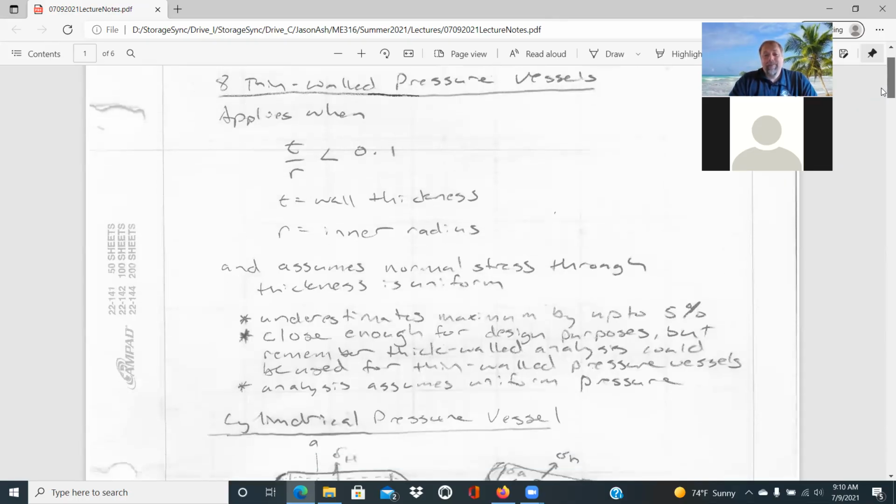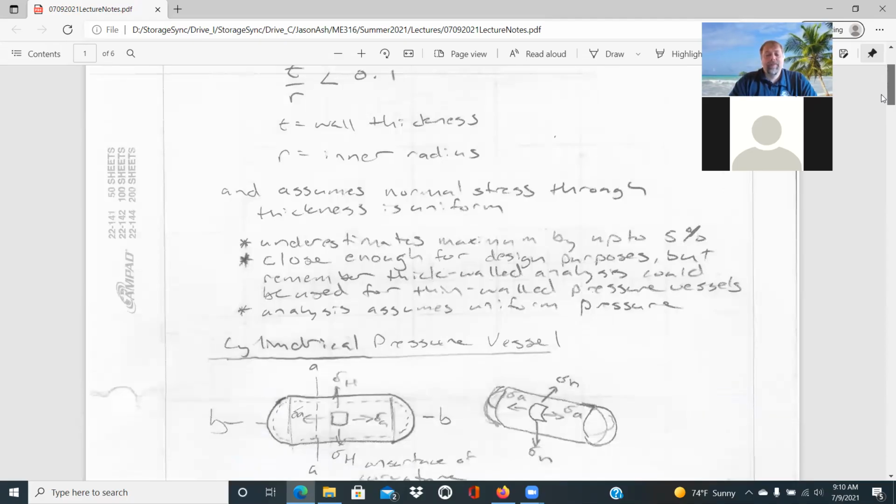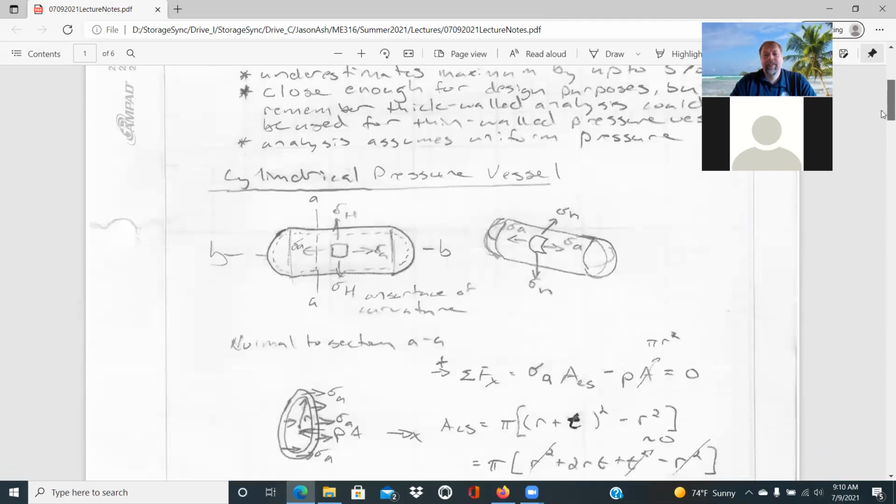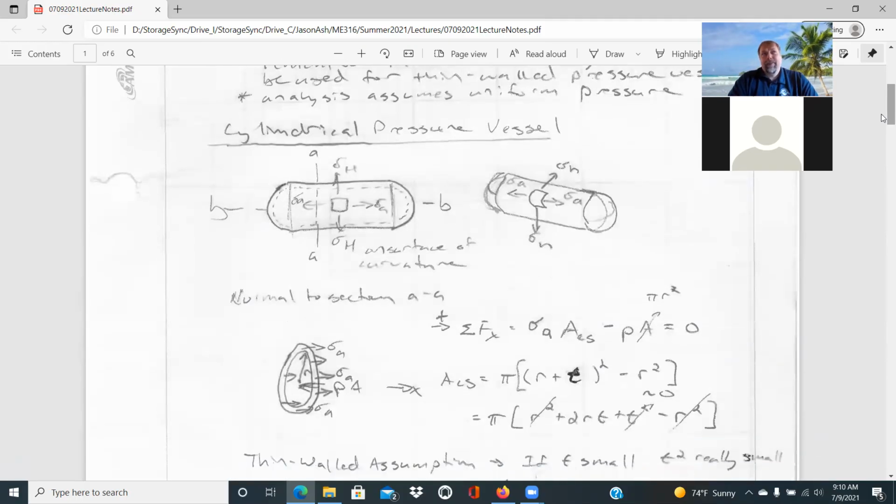For the analysis that we're going to do here, we're going to focus specifically on internal pressure vessels. And then in machine design, when you look at thick-walled, that can be applied to both externally pressurized and internally pressurized vessels. From a mechanics of materials approach, that's the method that we use with Hibbeler's textbook. We can look essentially at an equilibrium summation of forces approach to estimate what the state of stress is.